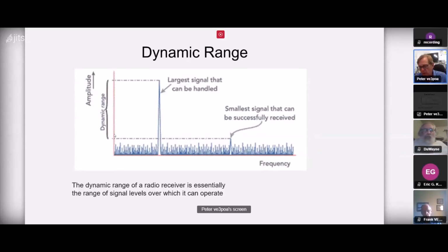Further ability and comfort in using KiCad. Fully developing the project to now include Gerbers, drill hole files, understanding better the ERC errors, and just a better way of laying out your various circuits in KiCad in a much more understandable way. Learning how to mill circuit boards, and then of course the FlatCAM and Candle programs that go with that. And a much better understanding of the receiver circuits and the whys you do this and the why nots.